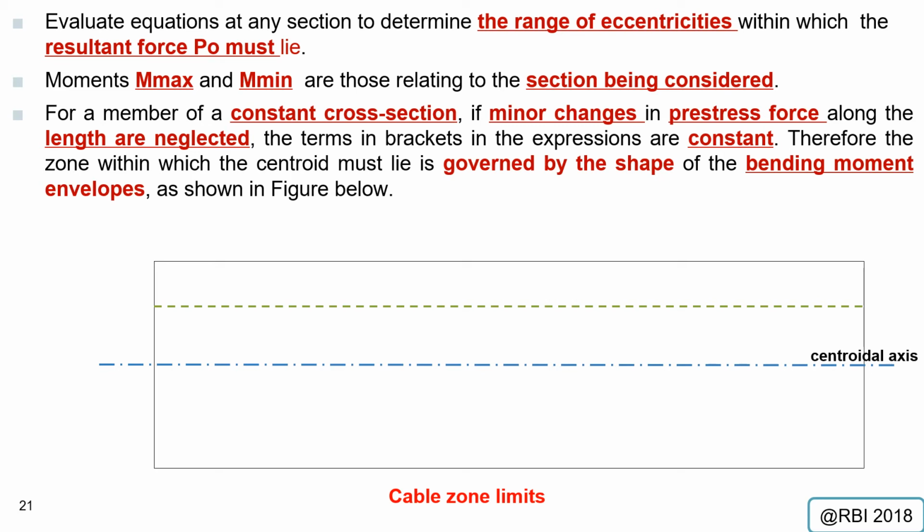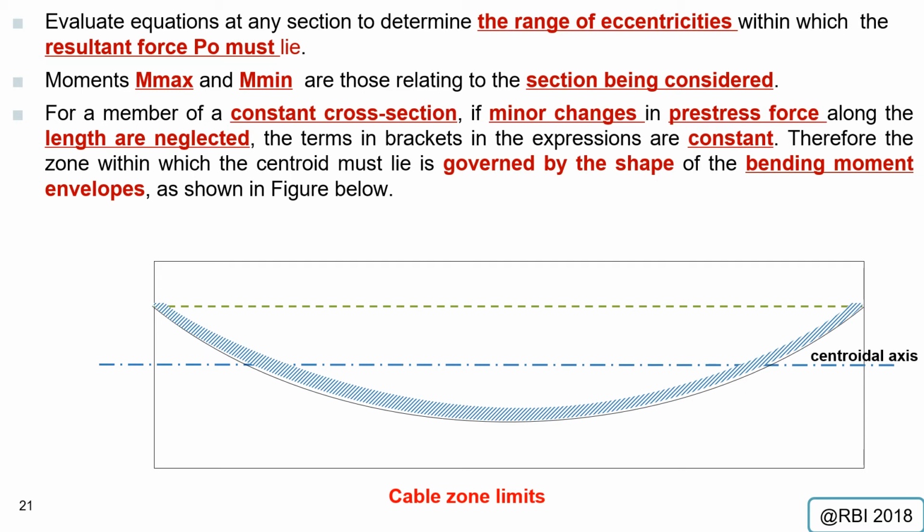Okay, so first, you have the beam with its cross-section, and you have to draw the central axis, the neutral axis of your beam. Then you start with the first line of the equation, which gives one tangent profile. It gives you the distance at the midspan, from the green line at the top to the tangent profile, of M maximum over k P naught.